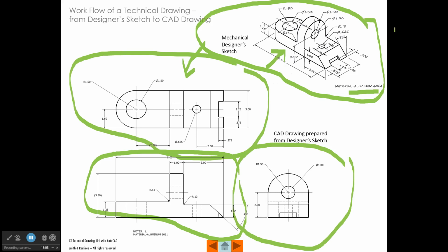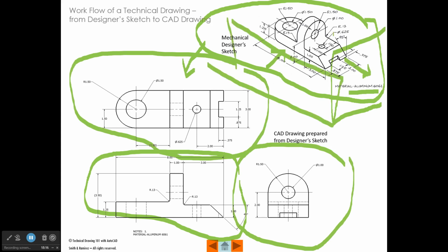And so just like I showed earlier, where we have a projection plane out here and you project to this projection plane, and we have a projection plane here, we project out to this, and that's what gives us this view and this view. And then we have a projection plane on the top. We project the view up to the top, and that's how we get the view that we see here.